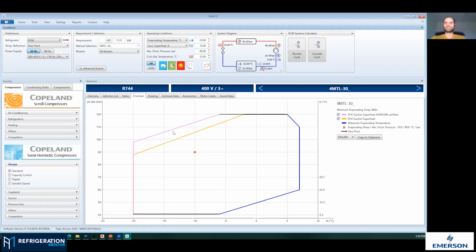But with today's new technologies from Copeland, the CO2 transcritical scroll coming to the market, you also have this beneficial effect of having vapor injection in the compressor, which can cool down your discharge. Yeah, I'm excited. But in HFC compressors, it was typically this area where you needed some head cooling or even vapor injection into the compressor to cool down the discharge.